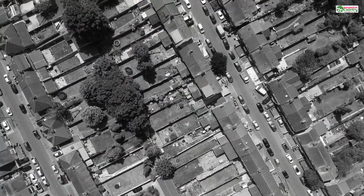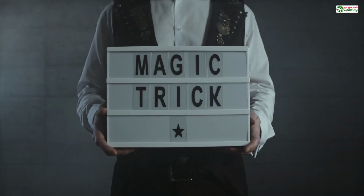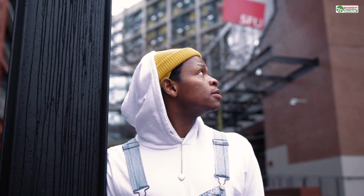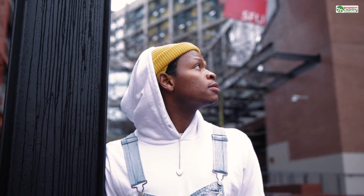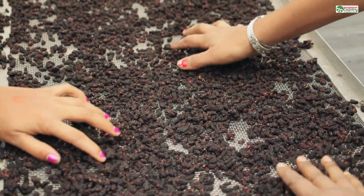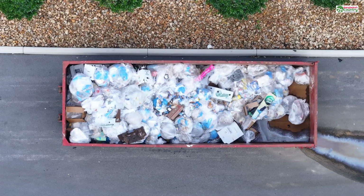For most decorative objects, things that will sit on a shelf and just look cool, like a figurine or a non-functional prop, you only need about 10 to 20% infill. This provides enough internal support to hold the top layers up and gives the model a decent feel in your hand without wasting a ton of material. Think of it as the bare minimum framing needed to keep the walls of a house from collapsing inward.